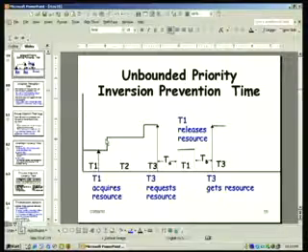task T2 started executing, and then another task T3 started executing, and so on. And the high priority task T3 requests the resource that T1 was holding, the same resource. So, naturally there will be a context switch, but T1 won't immediately start executing, because T2 was preempted by T3, and in between there may be several other tasks that might come in.